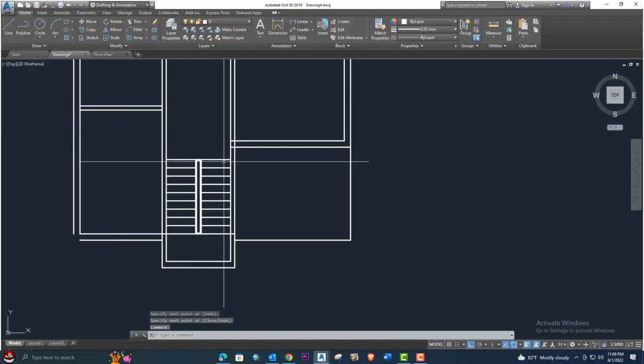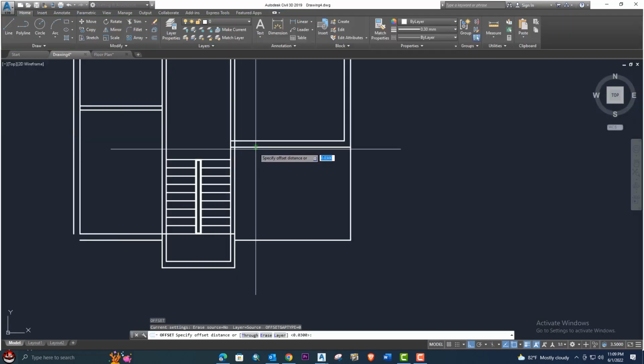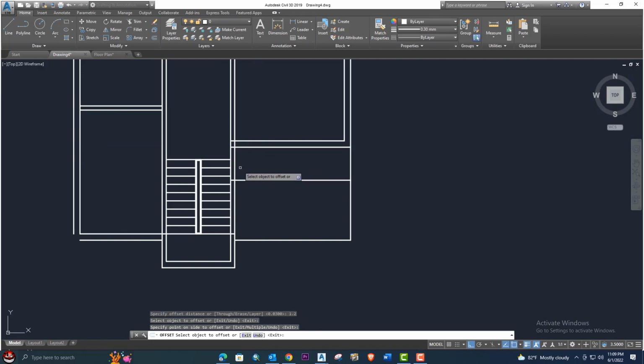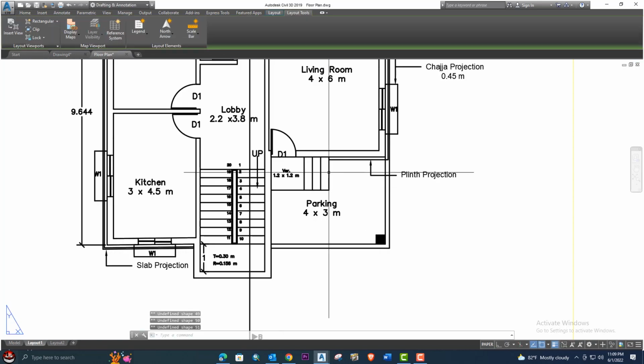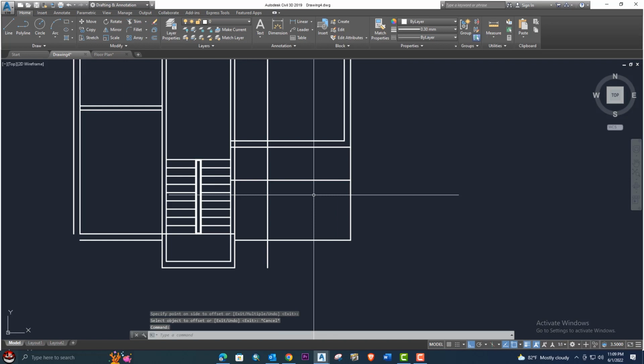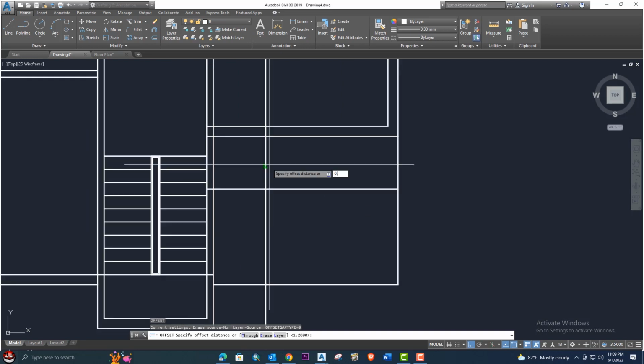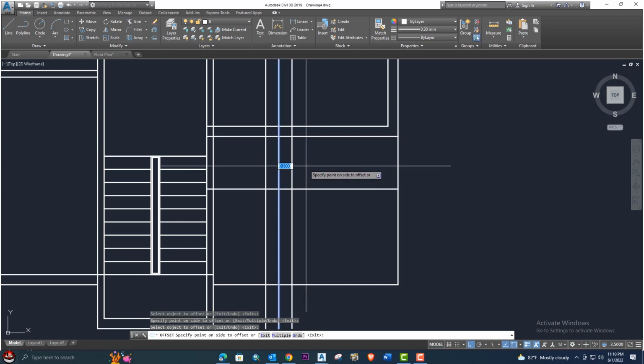Okay, go here to the drawing of our offset and enter 1.2 offset from this line and offset from this line. Okay, and next we have these threads for the stair 1 2 3. Okay, go to this option and enter of our offset for thread 0.3, enter, and 1 of our offset 0.3. Okay, select 1 2 3.